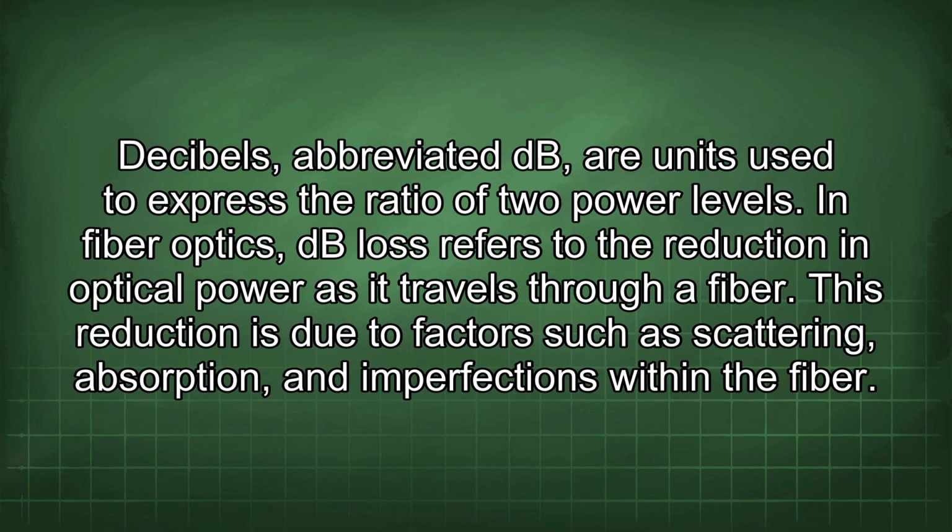Decibels, abbreviated dB, are units used to express the ratio of two power levels. In fiber optics, dB loss refers to the reduction in optical power as it travels through a fiber. This reduction is due to factors such as scattering, absorption, and imperfections within the fiber.